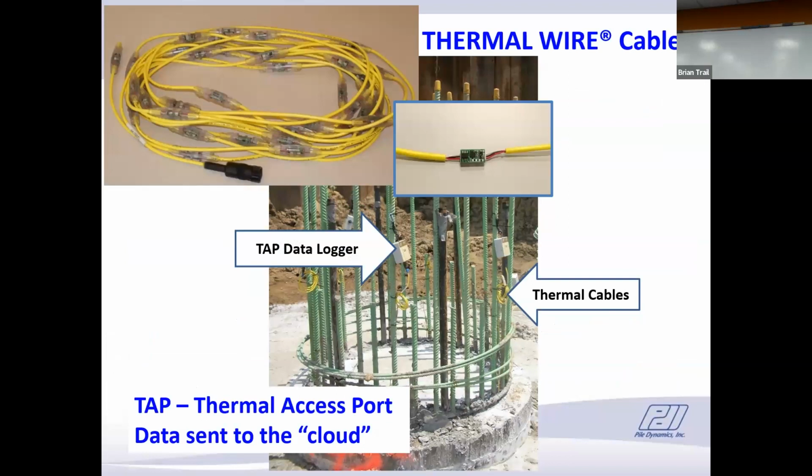So now the device more currently looks like a small temperature chip on a wire that we encapsulate for waterproofing. And every foot there's a temperature node. They're attached to the rebar cages and then attached to a data logger for each one of those. Each one of those then sends the data up into the cloud so that you can watch the temperature develop as the pile cures. So if you're an insomniac and want to get up at 2 o'clock in the morning in your pajamas, you can go look at the status of your shaft.